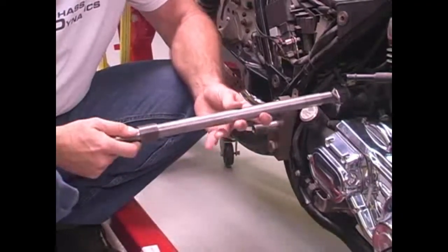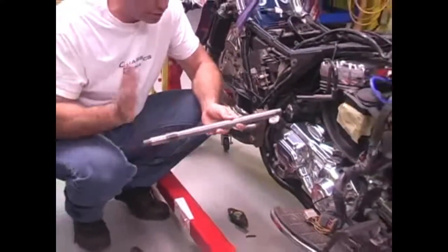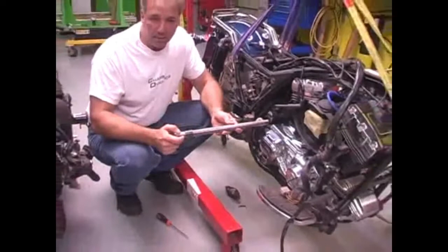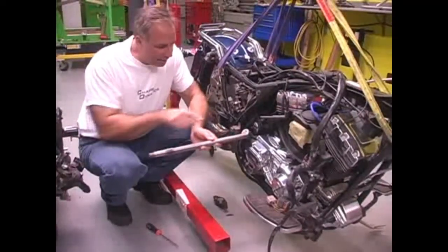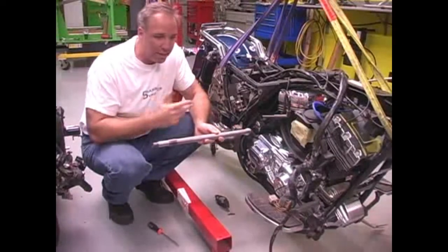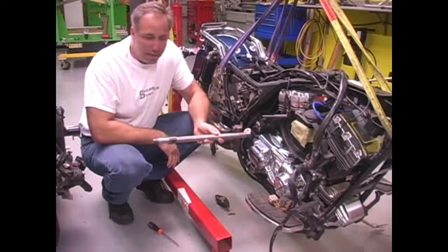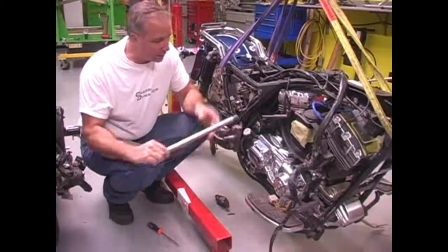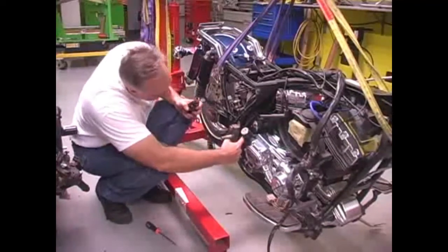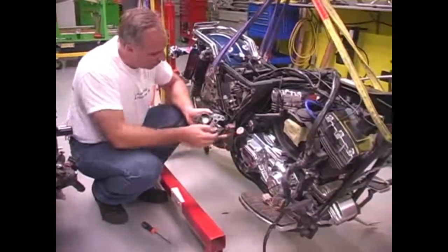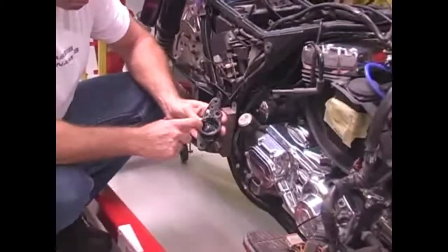We would torque this so that this would have 15 foot-pounds of pressure on it, just like a normal, when the swing arm pivots in the bike. We would put this end and this end into the tooling on the jig, center it up, and begin to straighten the bike from there. On this Harley Davidson, since it's rubber mounted, and what we mean by that is back in here, you can't really see it right now, but back in there is an elastomer cup that fits into this boss here.